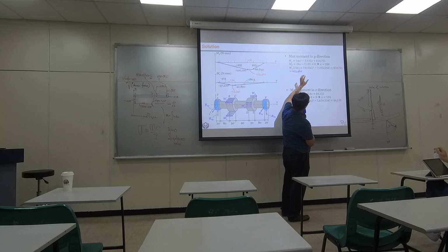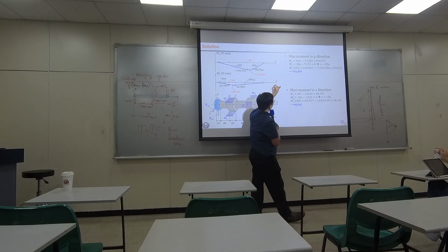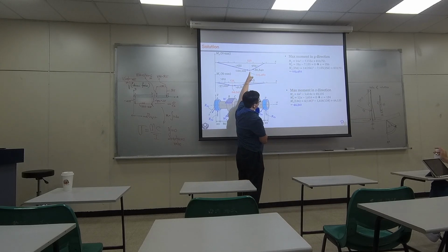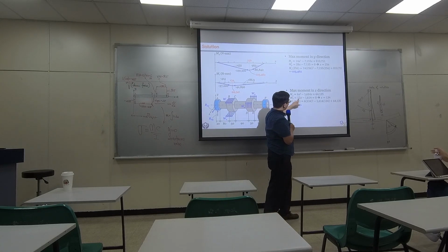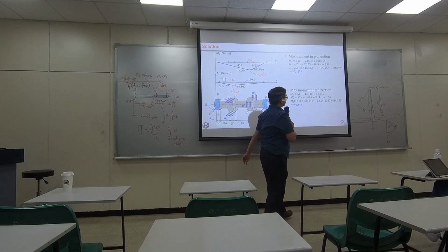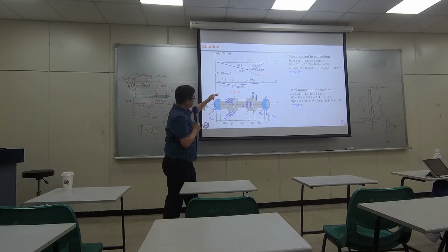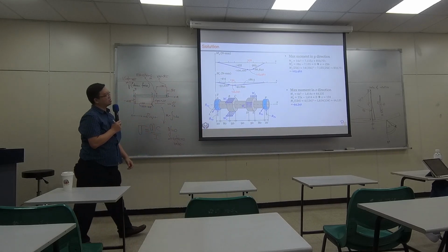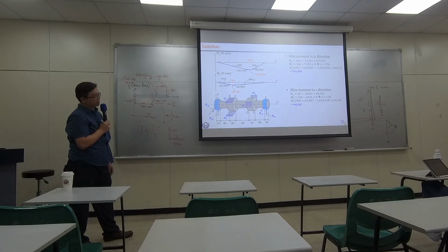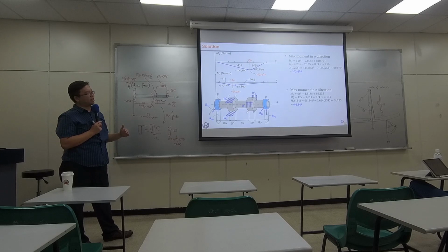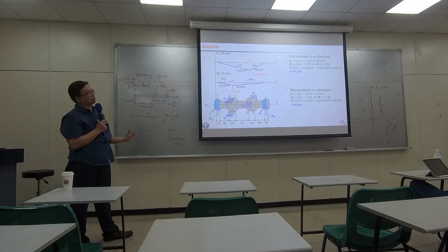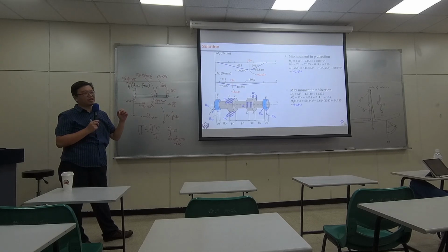And that gives me the exact position where we have the minimum. Same here, take the first order derivative and make it equal to 0. I get the position with the minimum moment. Actually, it is the most negative moment, and that actually is the largest moment. But negative represents compression.